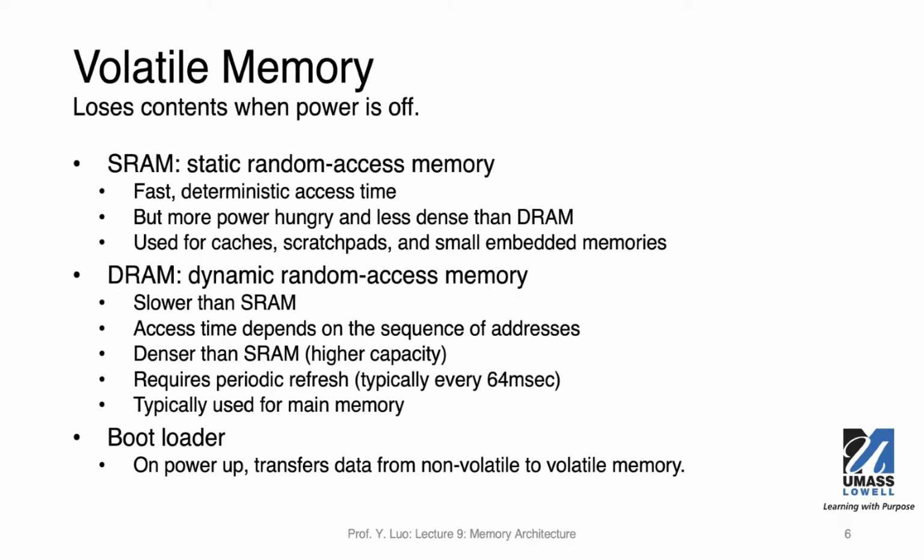DRAM is more popular because it's cost effective. It's slower than SRAM, but you can pack a lot more bytes in a single chip than SRAM. It requires some periodic refresh, and is typically used for main memory.